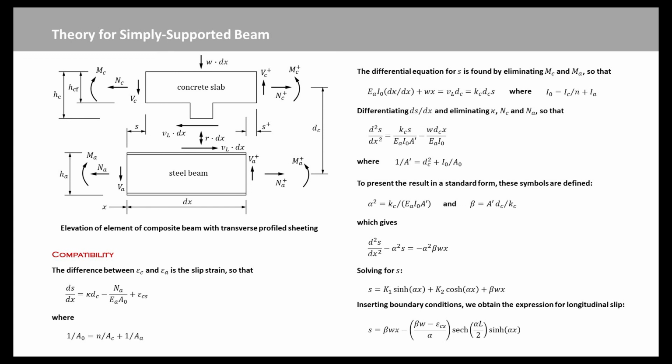In full interaction analysis, the slip is 0, and the results depend only on the bending moment and shear force at the cross-section considered. Here, they depend on the loading, boundary conditions, and shear connection for the whole beam.